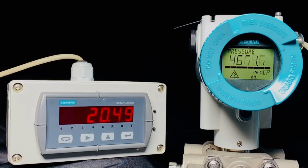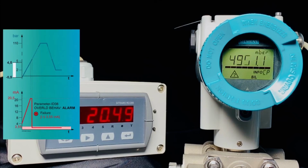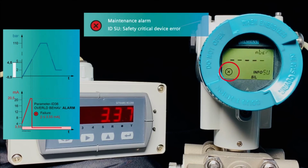If I increase the pressure further, the NE 107 symbol circle with the cross appears, which stands for device status failure. Info displays SU, safety critical device error. The current is less than 3.55 milliamp.